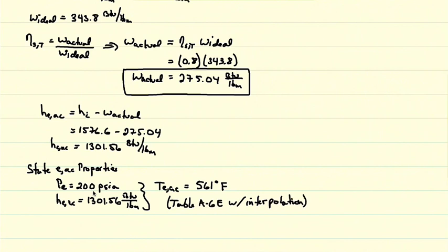Okay? And again, just to reiterate, if you're not seeing how to take these two values of pressure and enthalpy and get temperature out of that with linear interpolation, then it's important that you come see me as quickly as possible. Okay, so that's our second item that we were asked to determine, right? We needed to find this actual exit temperature, and so we managed to do that successfully.